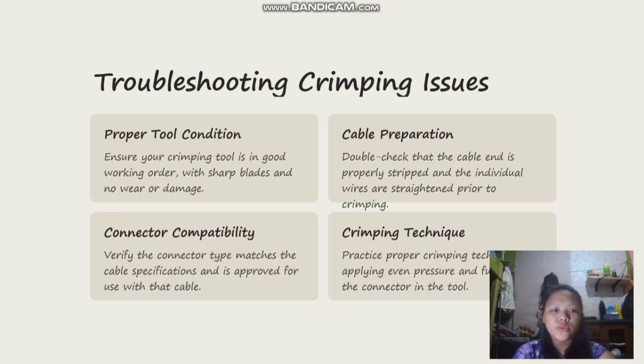Troubleshooting crimping issues. Proper tool connection. Ensure your crimping tool is in good working order with sharp blades and no wear or damage. Cable preparation. Double check that the cable end is properly stripped and the individual wires are straightened prior to crimping.